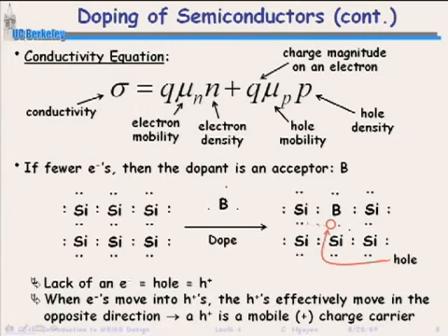So what is mobility? Mobility is not just how fast the electron can rocket through all of these things. When the electron moves, or the hole moves, what's it really doing? It's really bouncing off of atoms, right? It's drifting from one point to another. So that mobility is a measure of how much bouncing that electron has to do to get from one point to another under electric field. If your mobility is high, it doesn't suffer a lot of collisions as it goes across. If your mobility is low, it suffers a lot of collisions and takes a lot of field to get that electron across. You get very little current for the same amount of voltage.